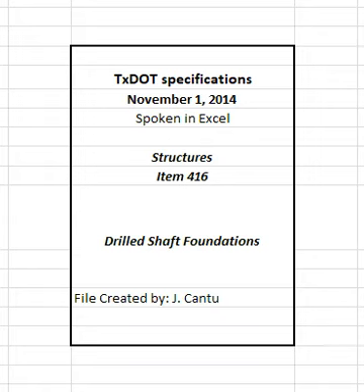3.5 Reinforcing steel. Completely assemble the cage of reinforcing steel, and place it as a unit immediately before concrete placement. The cage consists of longitudinal bars and lateral reinforcement, spiral reinforcement, lateral ties, or horizontal bands. Connect individual segments with couplers or by lapping steel as approved if overhead obstacles prevent placement of the cage as